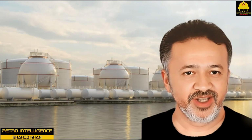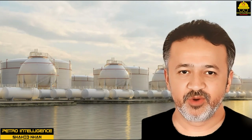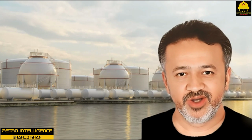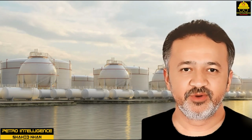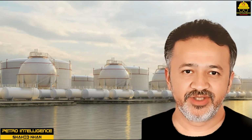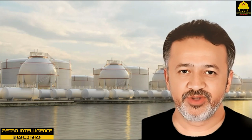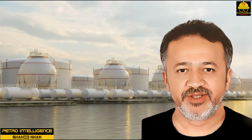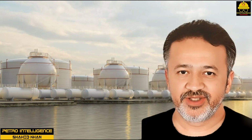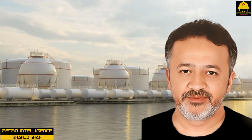The process technician has control of pressure, temperature, and process changes that might affect the amount of corrosion. The frequency and extent of inspection depend on factors such as pressure, temperature, the corrosive action of the materials handled, the materials of construction and their corrosion resistance, and past experience with the equipment involved. Equipment in high pressure, high temperature service subject to corrosion is inspected frequently. Some equipment may require complete inspection only once in 5 years. Visual inspection is the method most generally used.